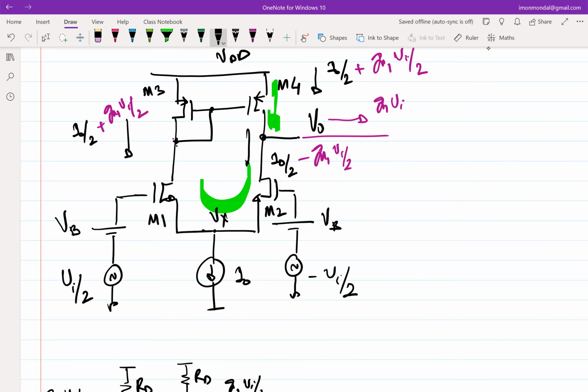The reason I added a capacitor is I wanted to show you that even without going into the fully incremental model, by removing all the sources, you can still do the analysis. If you just short it, yes, small signal analysis is still valid, but your total current equations are no longer valid, right?